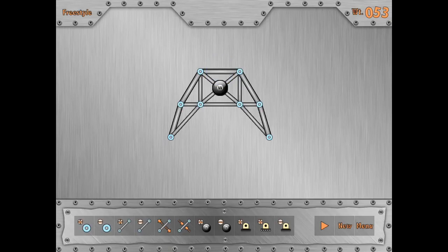So let's keep in mind that the weight of the structure at this point is roughly 53 kilograms. Let's see what we can get by optimizing our structure a little bit. Let's start by removing the top bar to give the overall structure more flexibility. Also, let's resize all bars to their original cross-section. By doing only these minor modifications, we can see that the overall weight of the structure was reduced by over 30%, with a new overall weight of 36 kilograms.